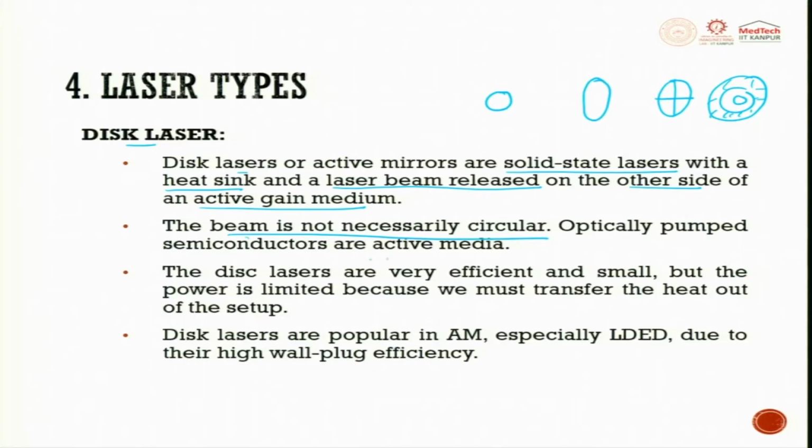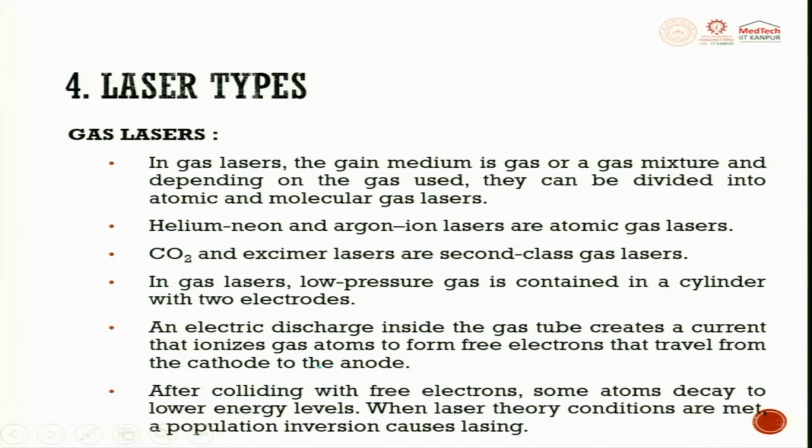Optically pumped semiconductors are the active media. Disc lasers are very efficient and small, but the power is limited because we must transfer the heat out of the setup. Disc lasers are popular in AM, especially LDED, laser directed energy deposition, due to their high wall plug efficiency. It is because of this that disc lasers are also effectively used.